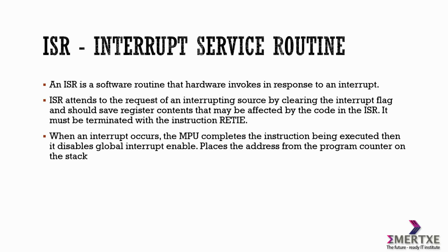ISR is interrupt service routine. An ISR is a software routine that hardware invokes in response to an interrupt. ISR attends the request of an interrupting source by clearing the interrupt flag. Whenever the interrupt happens, the microprocessor unit or microcontroller unit flags that interrupt and runs the next instructions, so that process will continue.